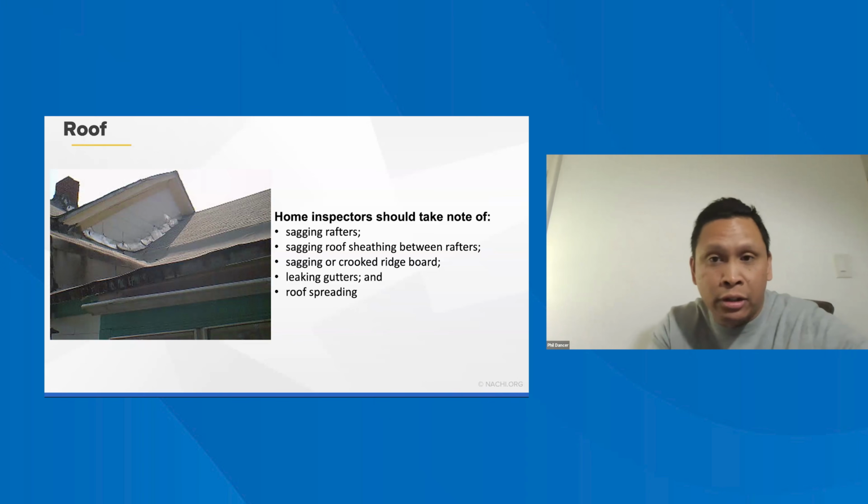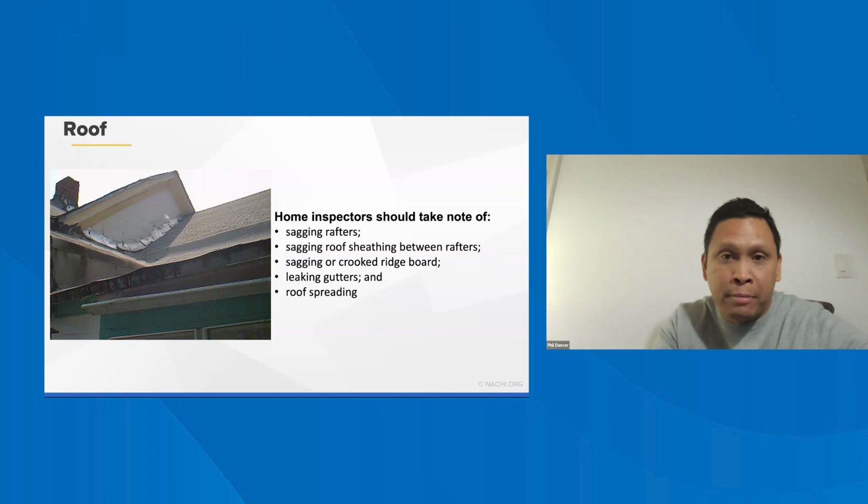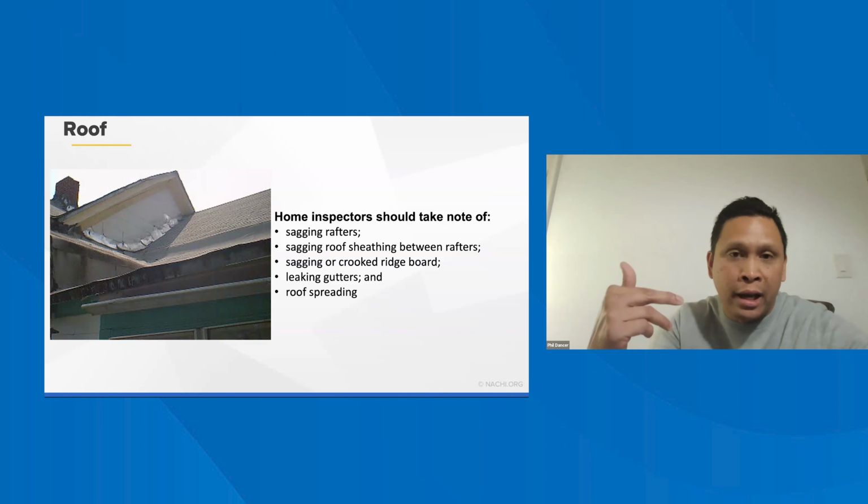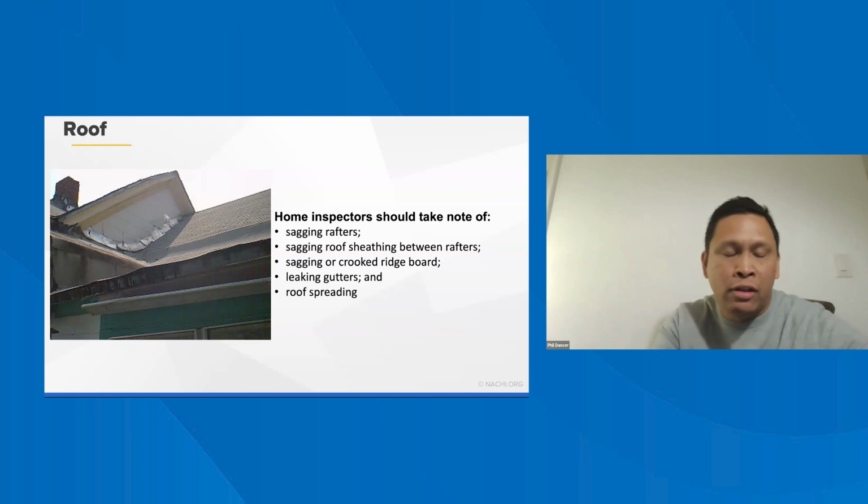An eighth of an inch, 16th of an inch, for those pieces of framing, because we want to try to prevent those things from happening. If you know the house was built during a certain time period and it's going to have a rafter system, and you see some roof spreading, or see something sagging, you know instantly in the back of your mind what you should be looking for when you either peek your head into the attic or step into the attic.